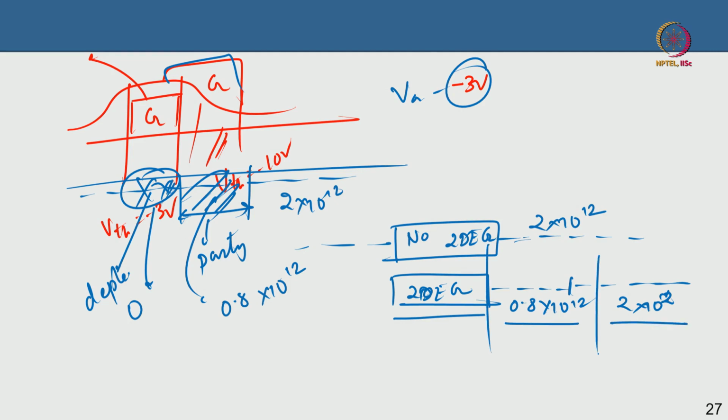This helps improve the field profile and improve the breakdown voltage, because remember, the higher the carrier density, the lower the breakdown voltage, in general, qualitatively. It is more difficult to deplete a highly conducting layer, and relatively much easier to deplete a lower doped layer. So this part is like a lower doped layer, and you can deplete it more easily without going to breakdown.